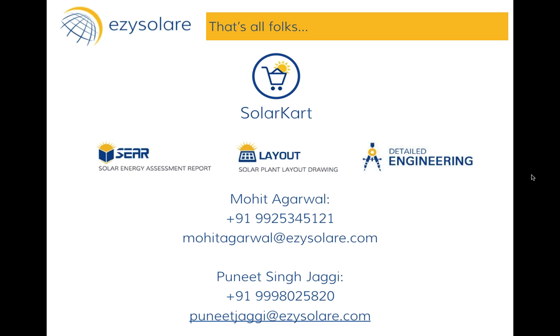At maximum, he can give a performance ratio guarantee. And again, it is not scientifically correct to ask for a performance ratio guarantee from an O&M contractor because he didn't build the plant. So at maximum, what you should ask him is an uptime guarantee. The risk of the sun not shining and because of that the generation being low is that of the owner of the plant, and the EPC contractor cannot do anything about it.